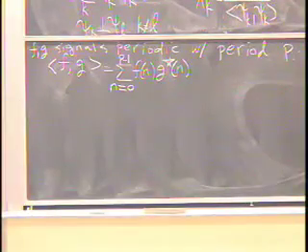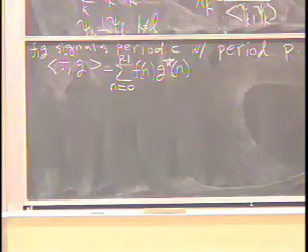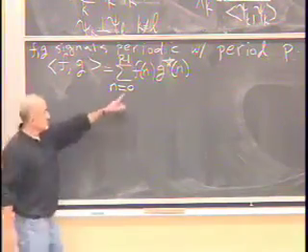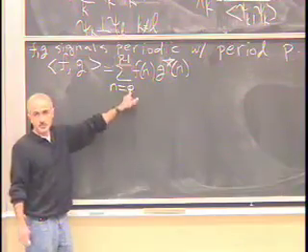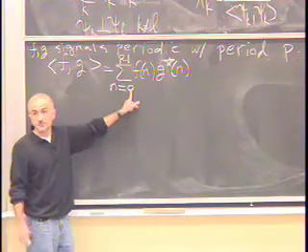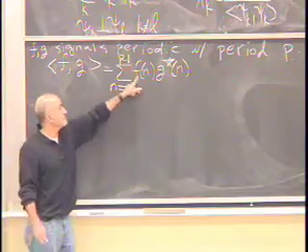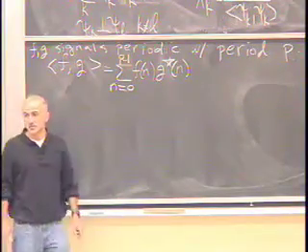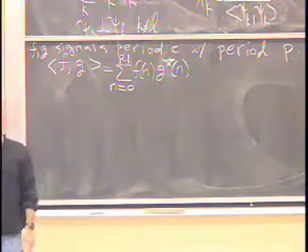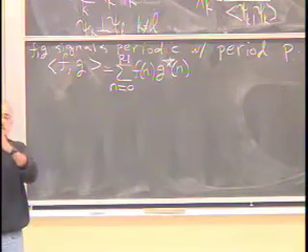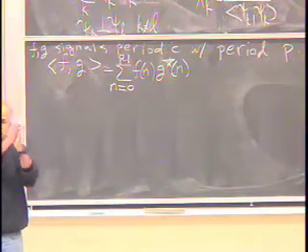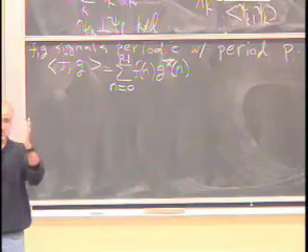That's the definition of an inner product of two signals that are periodic. One thing I should mention, though, is that there's nothing sacred about this particular choice of interval. I've picked the interval 0 to p minus 1. It doesn't have to be that way. I can pick my period to be anywhere, as long as I pick p contiguous samples of the signal.